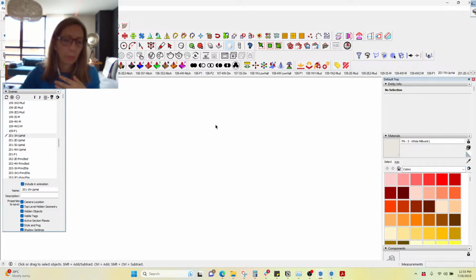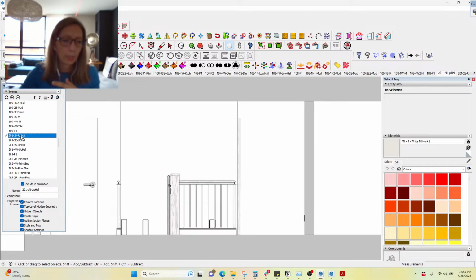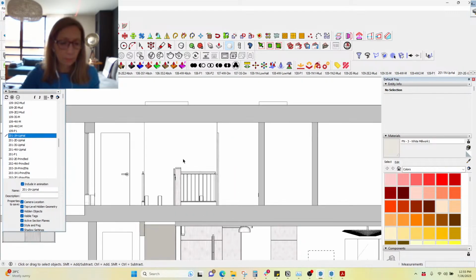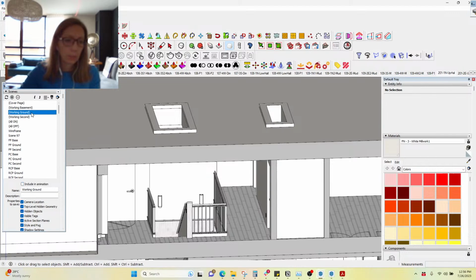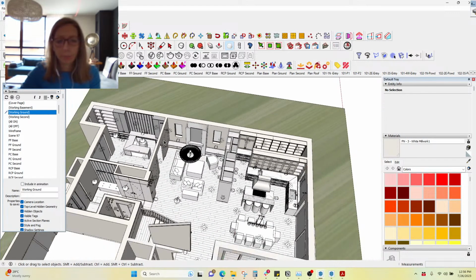People get afraid to do a lot of sections in their model because maybe they think it's going to make it messy or complicated, but I literally never see the sections, because if you did see all the sections, you would have to turn them on for some reason. The only section that's ever on for me is the one that's on in whatever scene I'm in. So they don't really ever get confused. They have a very specific naming protocol. They're only on when they're supposed to be. And I don't need to split my model up into many different files.